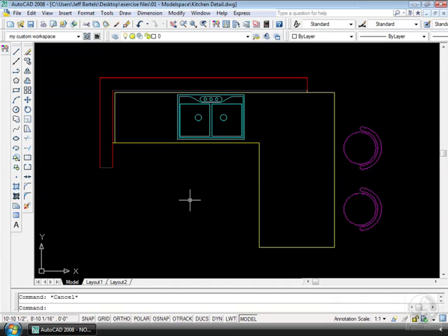I'd like to make some changes to the way my AutoCAD is functioning. One thing I'd like to change is I'd like to remove these scroll bars. I really don't need these anymore. I'd also like to change this highlight feature. Notice as I move over this geometry, even if I don't have a command running, these things are kind of flashing and popping up on my screen, almost like a light show. Let's make some changes to our settings.